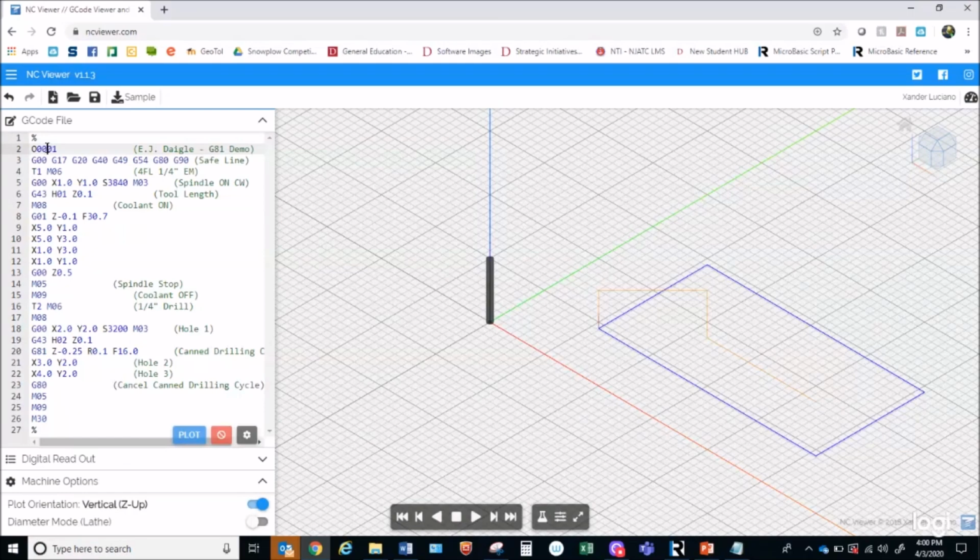I'm going to just go through this real quick. I'm up at the top. I'm going to highlight line 1 here, and then I'm just going to hit my down arrow. And I can watch what's happening to my cutter. You see it move over to the 1-1 position. And then it sets the tool at 0.1. And then it dives down into the part. And now it's going to trace around that rectangle. Boom. End mill's done.